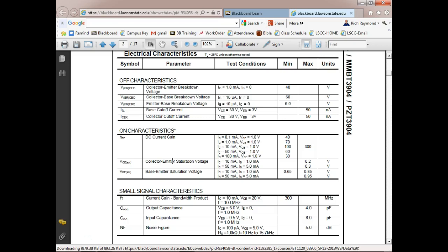So when we get a transistor and use it as a saturated switch, we're going to use minimum beta, and then we don't worry about it, right? If I use 100, it might saturate down here in Alabama, but up in Michigan in the wintertime, it's not going to saturate. If I use 30, it saturates in Alabama, it saturates in Michigan, and it saturates up at the North Pole, because it is guaranteed. You understand that? So we use minimum beta.